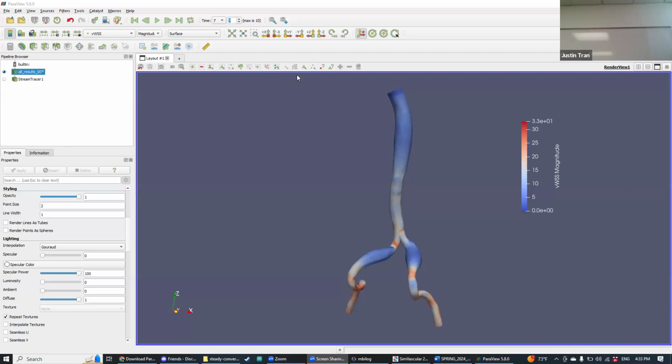When I walked in, I could hear those. Use the resistance. Yeah, so go to your inlet and outlet boundary conditions. For you, you have a lot more, so that's going to be a challenge. But you need to basically determine which ones are out. For the outlet ones, you have to change the type. So if you double click on that platform, click on the down arrow, you can see that we're basically only going to be worried about the first two.